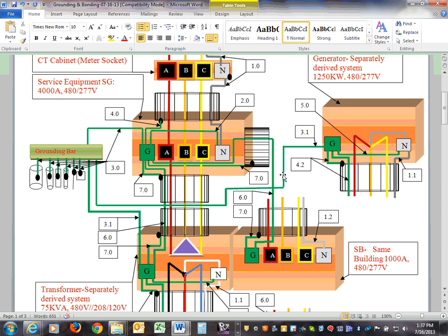You don't need a wire. So if your system is 480/277, all you have to do at the end of the conduit is have a bonding bushing, and you tie the conduit directly into the grounding bar inside that panel. If your system is 208/120, there is no need to do anything. The locknuts that you have on the EMT conduits will act as bonding the conduit to the box. So there are a few ways of doing this without putting a wire there.